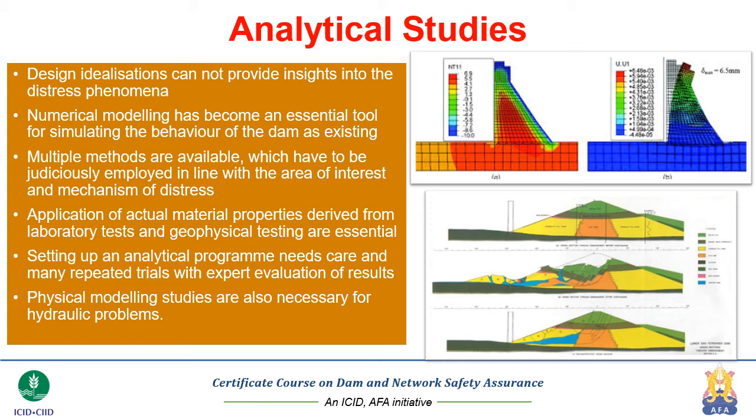Another major aspect of departure is in the seismic part of the behavior of the dam. Because dam is an elastic medium which is sitting on another elastic medium, that is the foundation, and these media are not indefinitely elastic, they are basically what we can call elasto-viscoplastic. And there are also discrete behavior of these individual elements because of the discontinuities that may exist. So all these kind of aspects have to be understood using the new numerical modeling techniques, which is an essential tool for simulating the behavior of the dam.